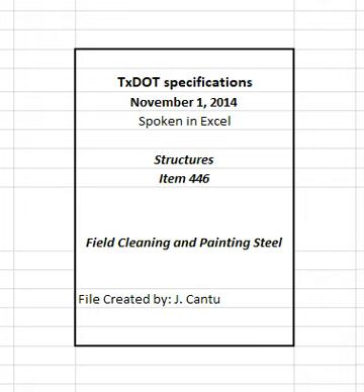Repair or completely remove and replace all paint that has been applied improperly, has been applied to improperly cleaned surfaces, fails to dry and harden properly, fails to adhere tightly to underlying metal or other paint film, or does not have a normal, workmanlike appearance in conformance with this item.